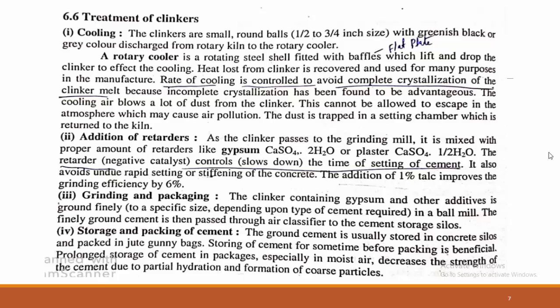This is very important. The cooling should be gradual, not sudden. The rate of cooling is controlled to avoid the complete crystallization of the clinker melts. Therefore, initially the clinkers are cooled, but the cooling should be at a controlled rate, that is, gradual cooling.